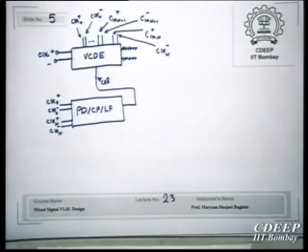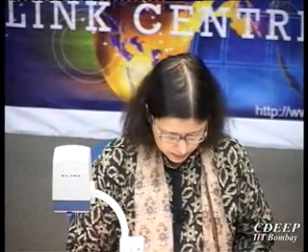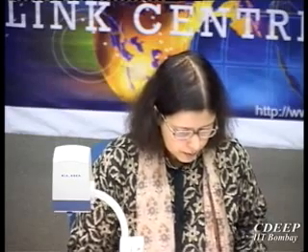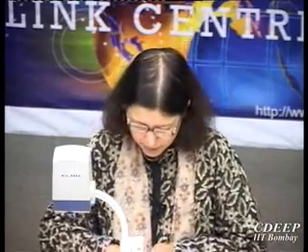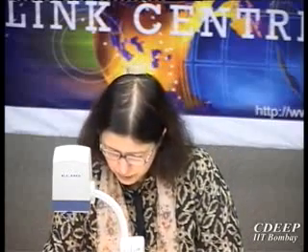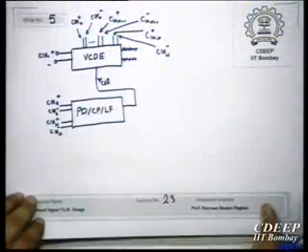Actually, how is the differential? We can, in fact, extend to a differential circuit. The benefit of differential is it is not sensitive to common mode noise, therefore we will get better performance. So what is an example of a differential inverter? Because actually a differential inverter is the basis of this ring oscillator.